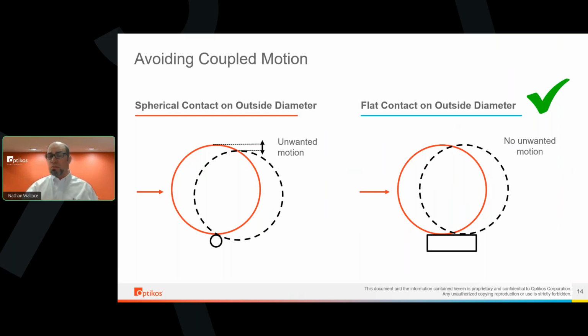I'm sitting in front of an interferometer. I'm looking at my Zernike polynomials. Hopefully, we've changed it from R theta to X and Y, so I have a really nice readout of, say, coma, for example. I have the X component, I have the Y component, and I have these orthogonal adjusters that are there. I can make a deterministic change to affect the X component of the coma and not adversely affect the Y component of my coma.